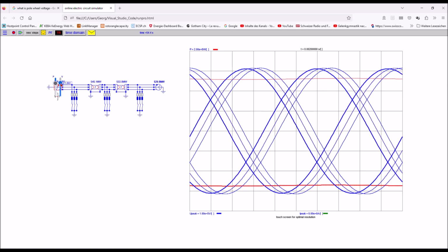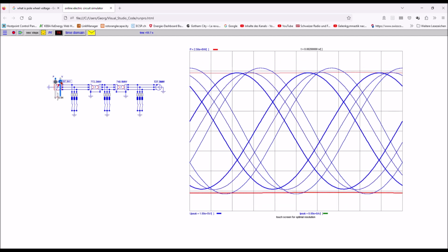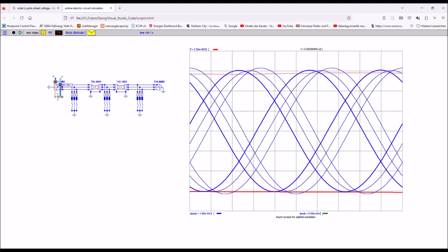The oscillation in the power trace you may have seen at the beginning of the torque increase is due to the temporary DC components, mainly through the reactors. By the way, there is this three-phase source without star ground, which can be used, for example, in cases you would like to simulate the effect of harmonics on a network.